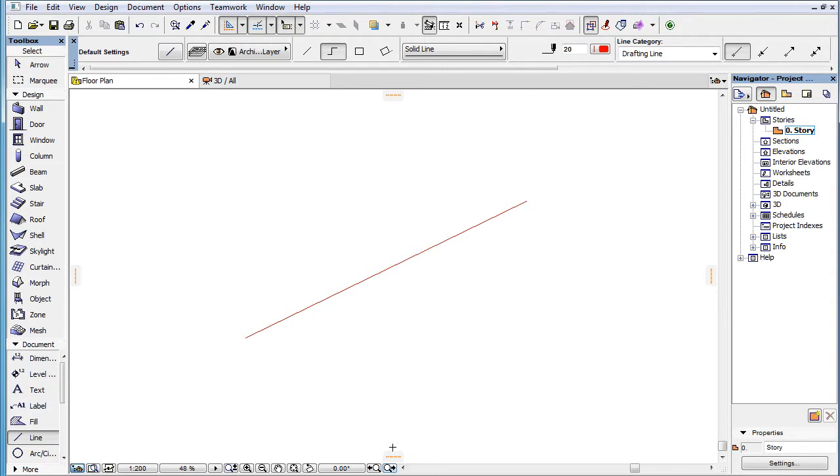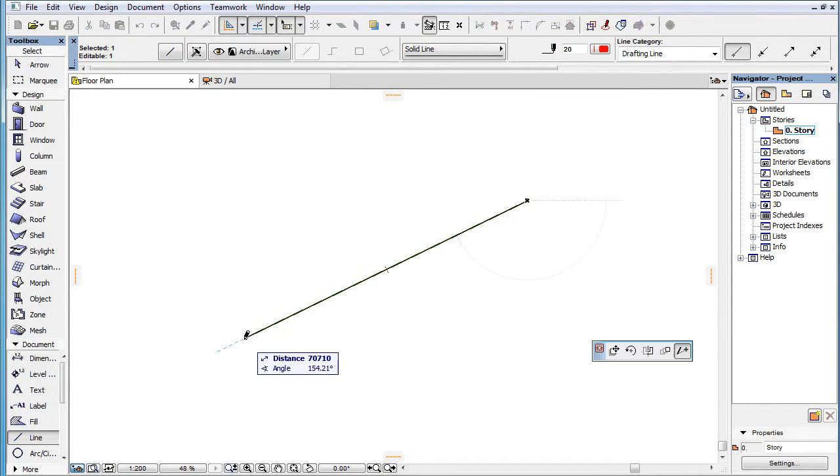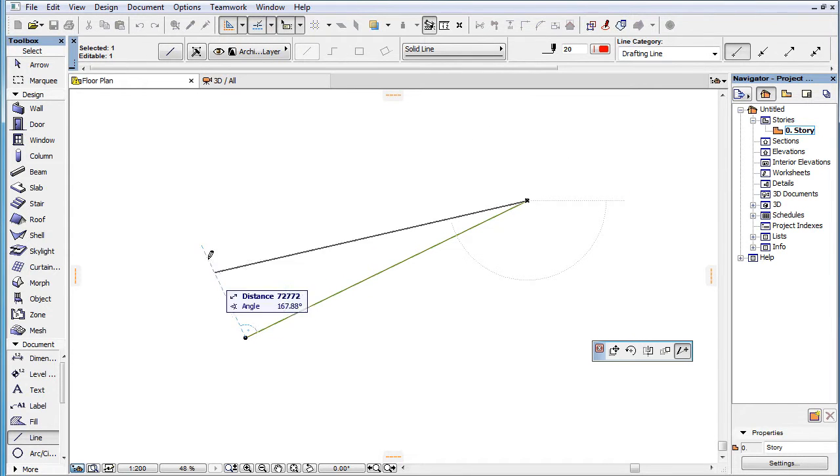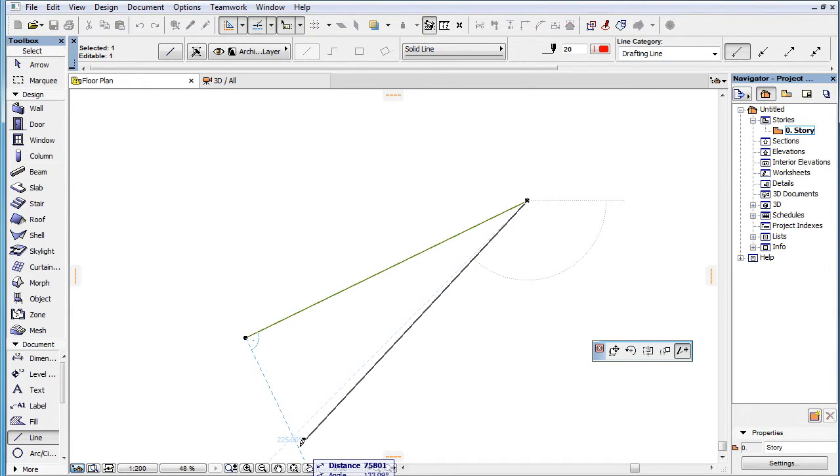If you're editing an element, the element edge and its endpoints are implicitly considered marked as snap references. This way, you can find the direction of the element edge and the perpendicular directions to the edge from either of its endpoints.